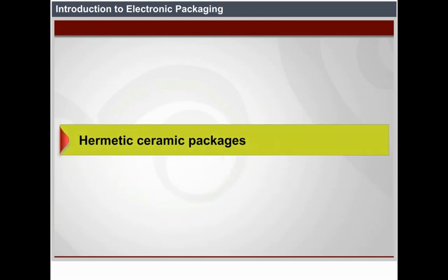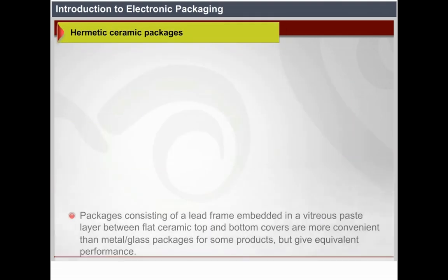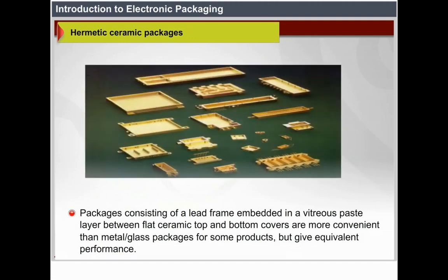Hermetic ceramic packages. Packages consisting of a lead frame embedded in a vitreous paste layer between flat ceramic top and bottom covers are more convenient than metal or glass packages for some products, but give equivalent performance.